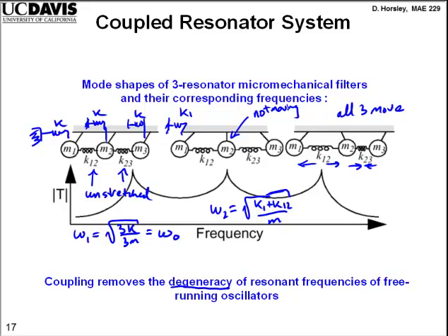Okay, and it turns out that we could actually do this coupling between resonators either using mechanical springs, the compliance of those springs, or we could couple them together using capacitors. If we talked about the equivalent circuit models, the compliances look like capacitors, and so we can either capacitively couple the resonators together, or we can connect them with actual springs. So this is how people make filters.